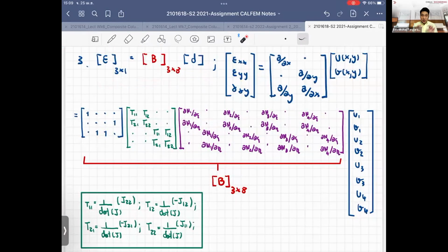So I just put all the jigsaw pieces together, which completes all the information that we have here. Basically, we define the strain as the first derivative of the shape function. This is the derivative form: the strain in x, the strain in y, the shear strain, and this is the derivative of the displacement in x and y. And we define the displacement in terms of the shape function. Then you derive them by taking the derivative of this, and then you can expand the forms.